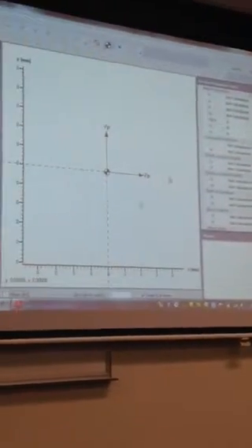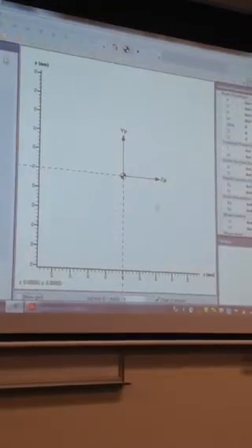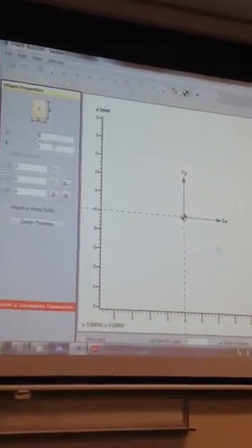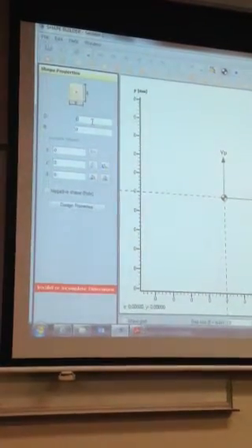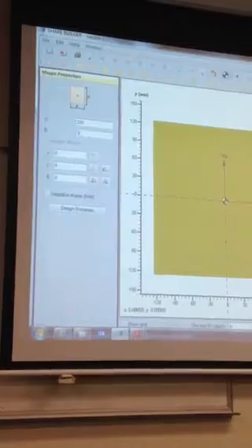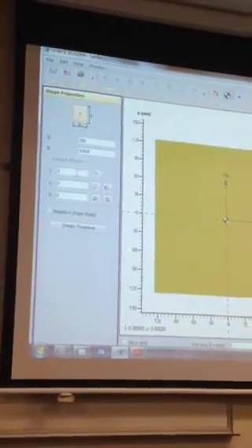But we're going to generate our cross section. So we're going to use the little section form here. It gives us a whole lot of different options. We're going to look at a solid rectangle. Its depth, we'll start with a 250 thick slab, and it's going to be a metre wide.